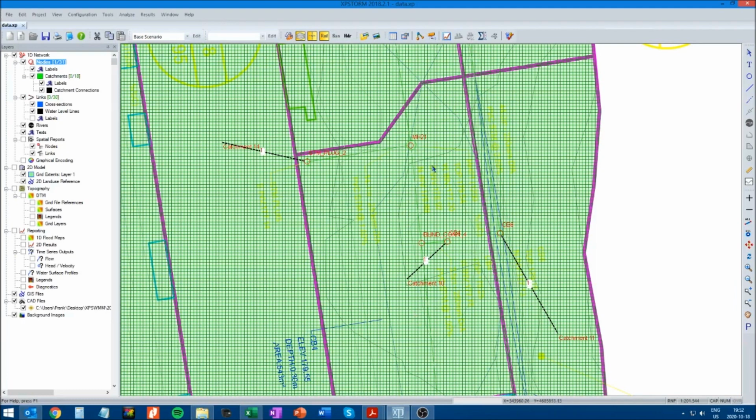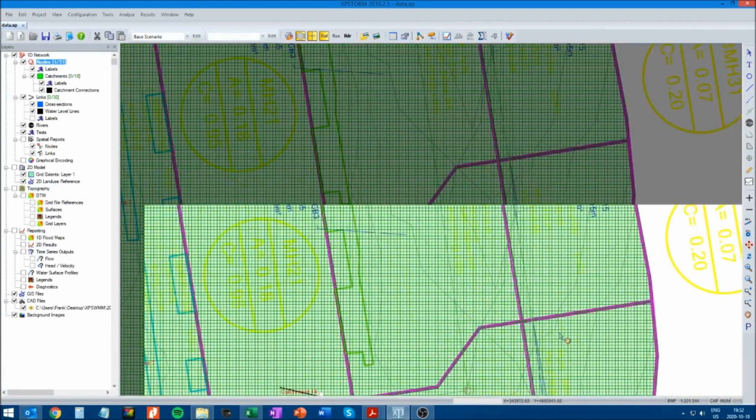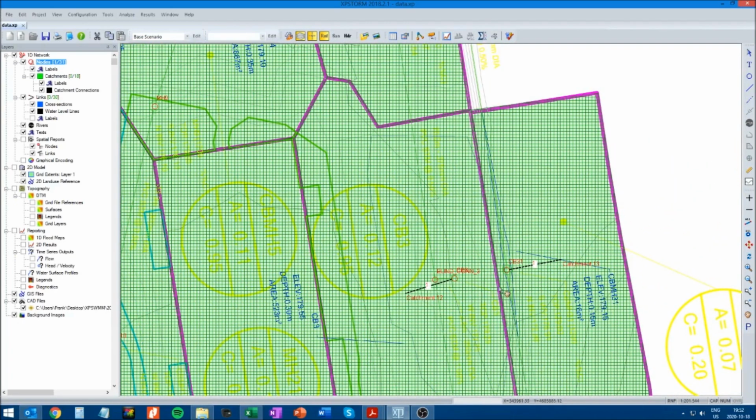So what we have to do is, still in the runoff mode, click on that structure and go to the left here and click the minus sign which says remove object from mode, and by clicking that it turns into a square and it's no longer part of the runoff mode. So for all of these that are not receiving direct runoff, you have to remove them from the runoff mode. So this one is getting runoff. This one is, so okay, here's a blind connection that's not getting runoff. So we take that blind connection out. The CB is getting runoff.